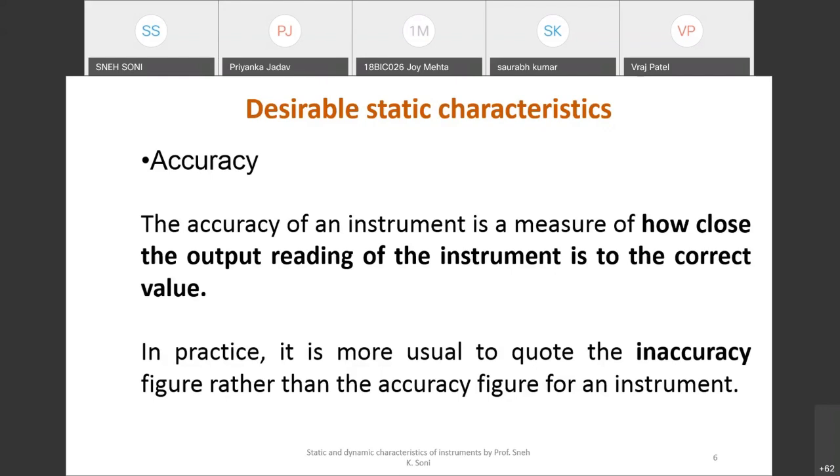But in practice, we are more concerned about inaccuracy. So we don't present percentage of accuracy, but we represent percentage of inaccuracy, right? So if we have inaccuracy representation, it is in the range of plus or minus this many percent of full scale, right? So the inaccuracy figure you will be getting, and that is more concerning for an instrumentation engineer.